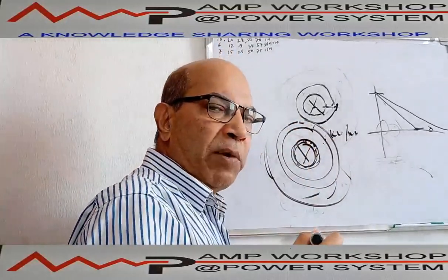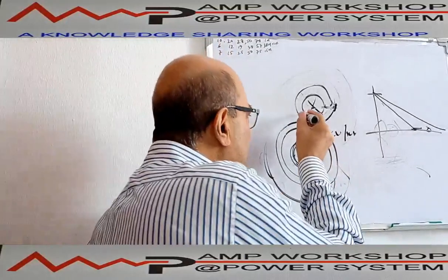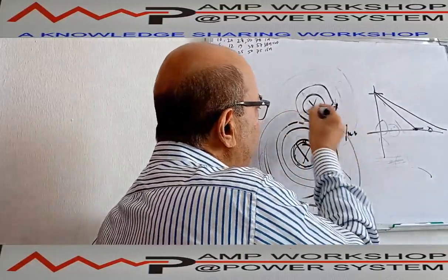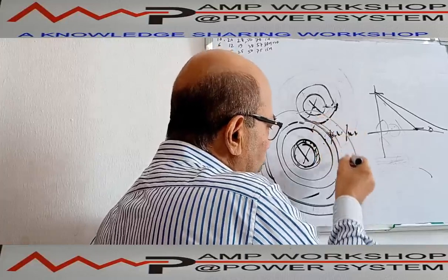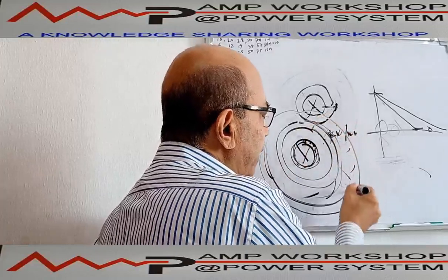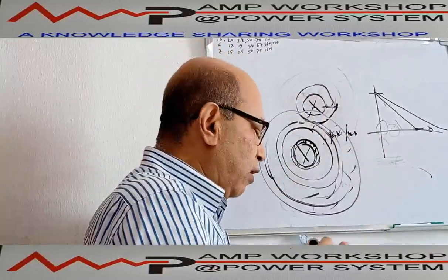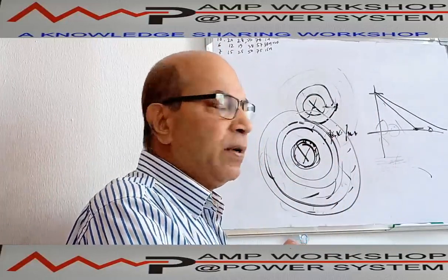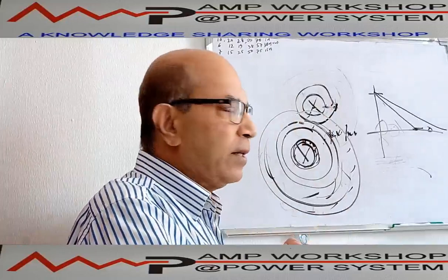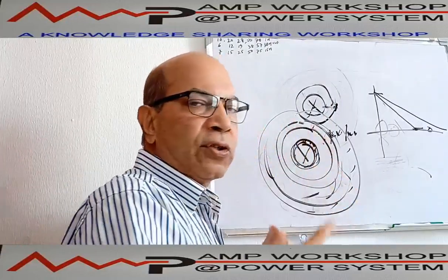And if we want a complete dry design, then we put a lead sheath over the cable: over this insulation and semiconducting layer we put a water barrier tape, then over here a lead sheath. After the lead sheath we go for the metallic tape, or the lead sheath can be used as the metallic tape, then we go for the further arrangement. So these are the basic construction of the cable.